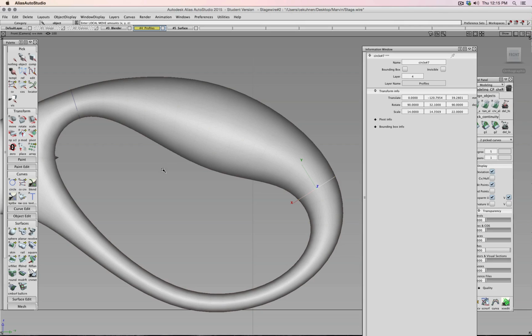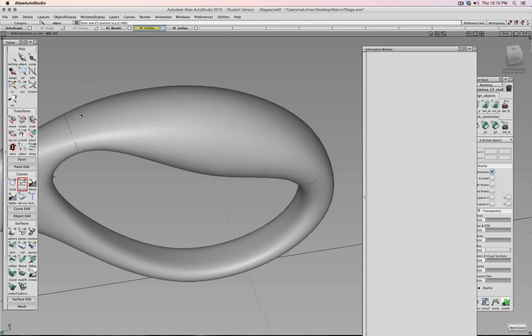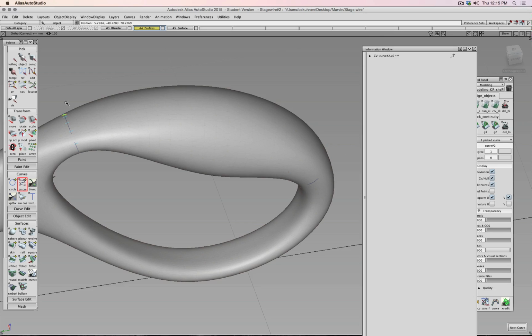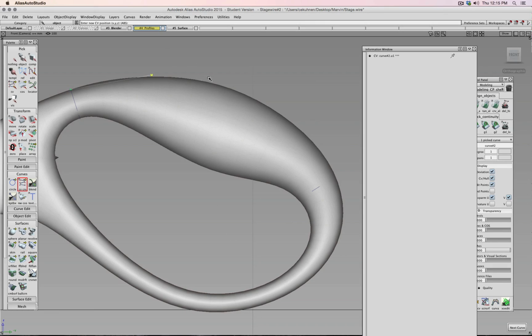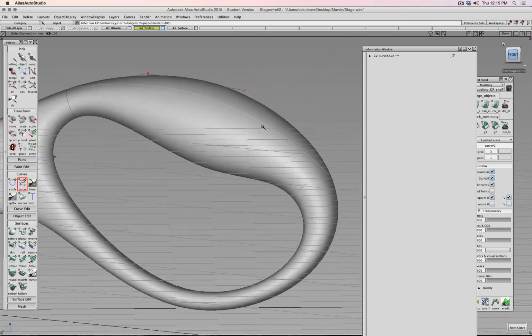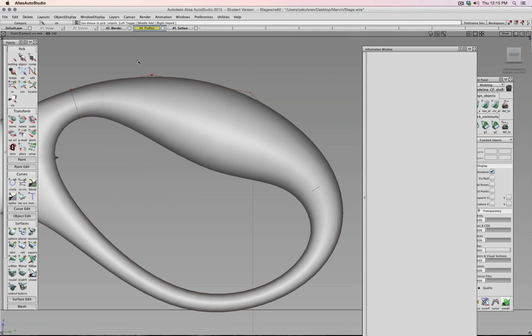Okay, so let's see. Could we, for example, solve this one with a rail? So I'm creating myself a curve. What degree do I have? Degree 3. I'm going to degree 5 here. And then 1, 2, and snap. Okay. And then I'm going to select those CVs, push them out, and try to sculpt kind of like this first arc I have here.